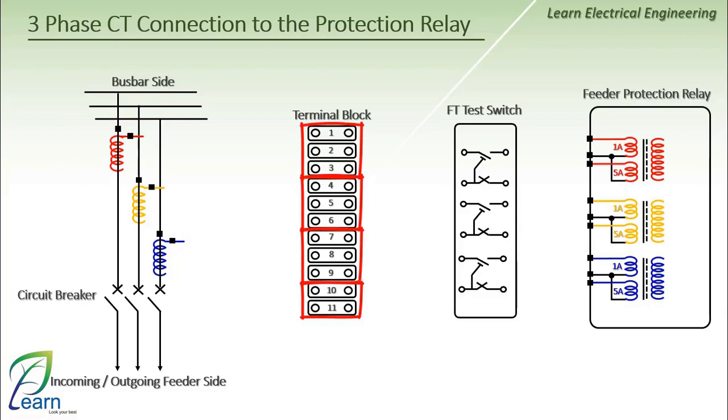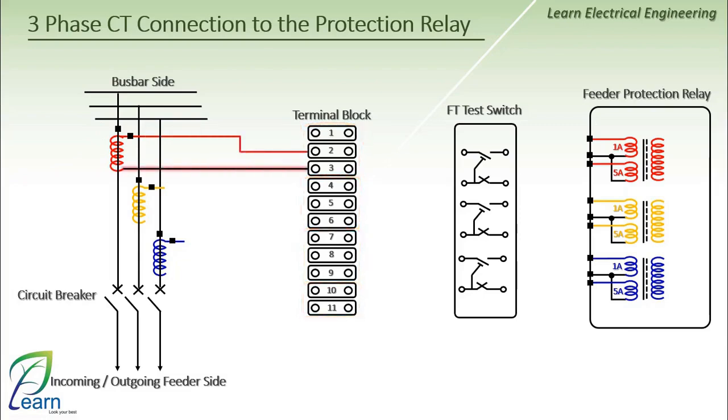Connect phase R to CT terminals number 2, 3, phase Y to CT terminals number 5, 6, and phase B to CT terminals numbers 8 and 9.